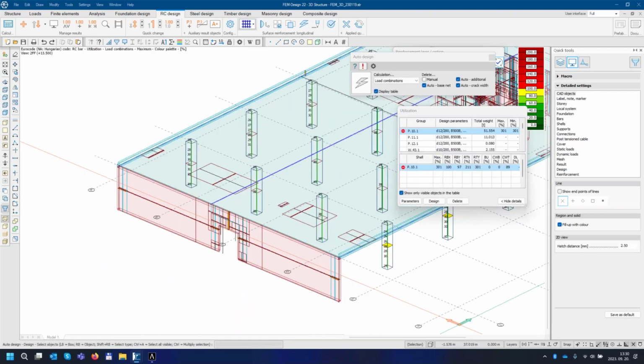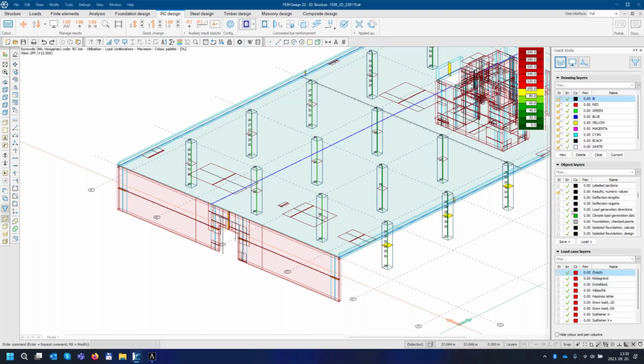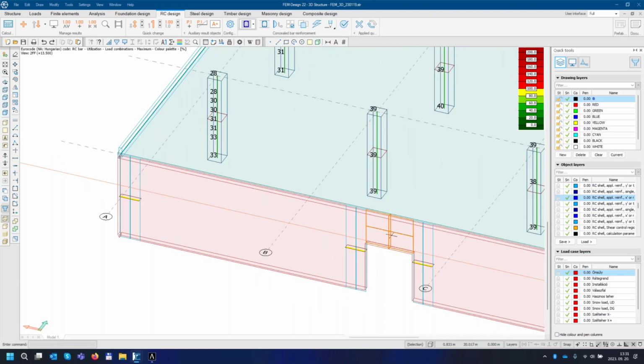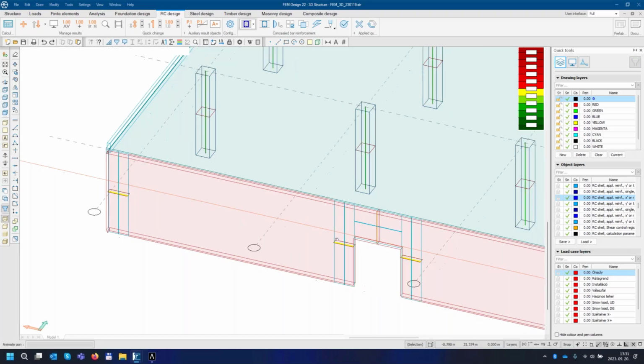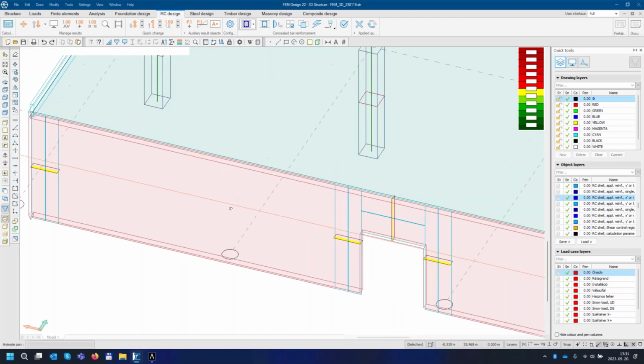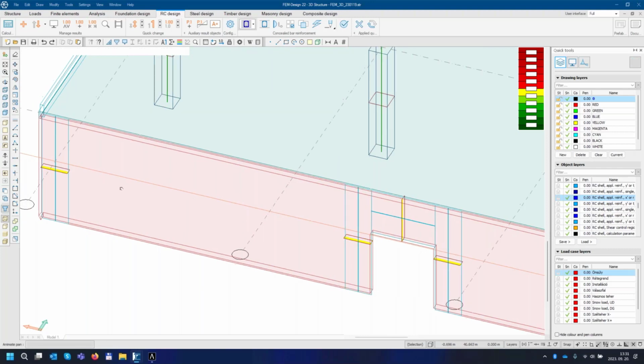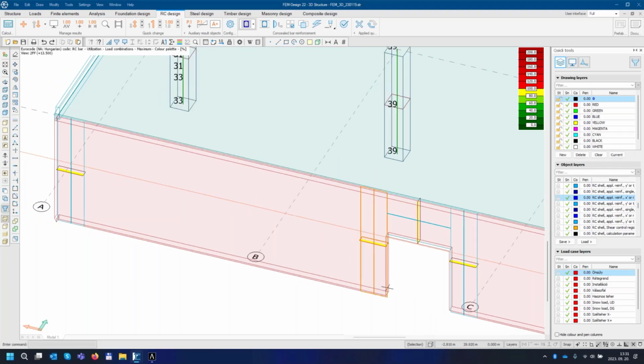You can use this mode to reinforce all the walls, but my special favorite is the concealed bar reinforcement, which is perfect for walls. If you make column-like and bar-like elements to the edges and to the sides of the openings, FEMDesign will convert the surface internal forces into bar-like internal forces.